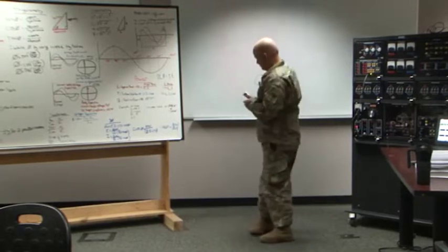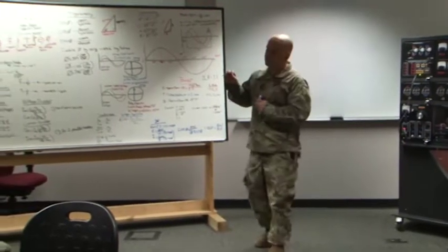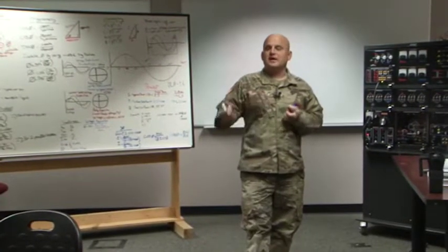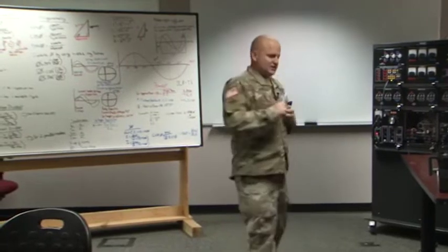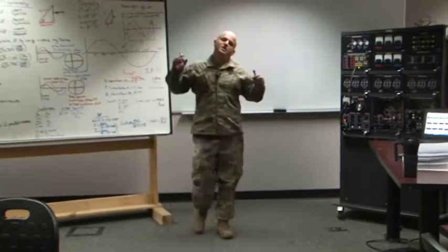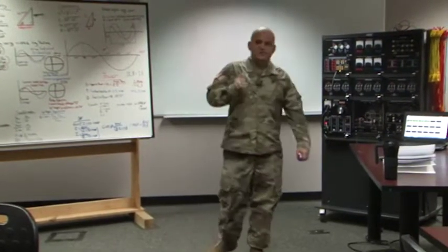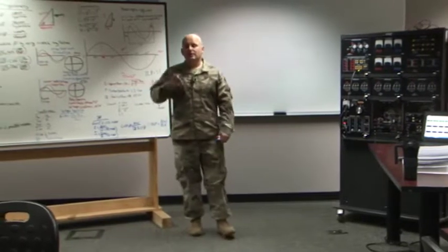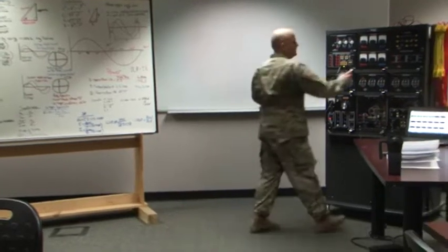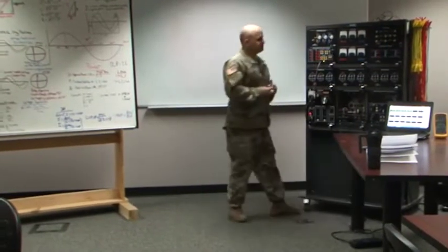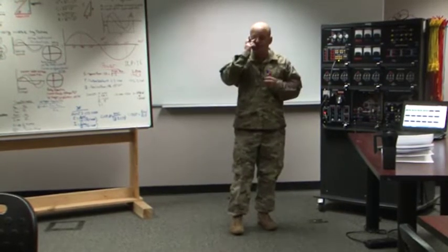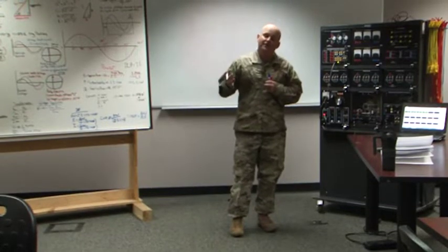Knowing what's going on in there helps you deduce and troubleshoot some problems that are out there in the field. So the three-phase transformer block is really just about the connections, some of the science behind the connections, and some varying connections. I don't want you to look at the three-phase transformer like one set of primary windings and one set of secondary windings. I want you to look at it like three individual single-phase transformers that we're now going to put together.